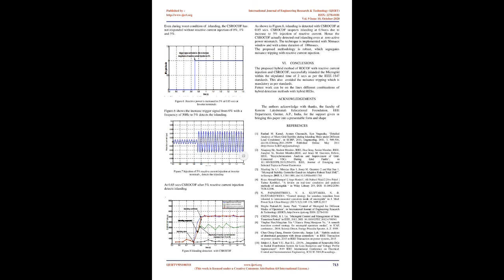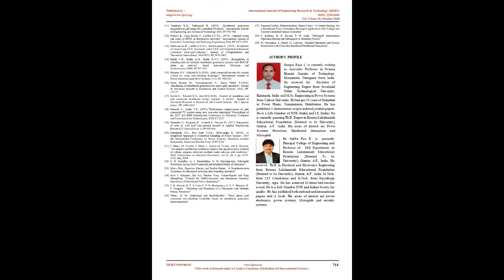MATLAB system model. The system parameters are shown in table 1. A PWM-based AC/DC/AC IGBT converter/inverter is the interfacing inverter of DG 20. DG feeds a load of 5 MW at 50 Hz. The MATLAB simulation model is shown in figure 2. The circuit parameters are shown in table 1. The grid-side inverter is synchronized to grid via PLL.